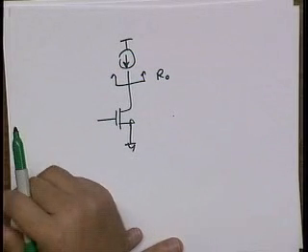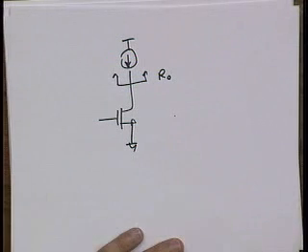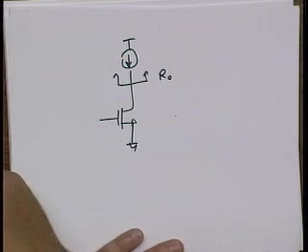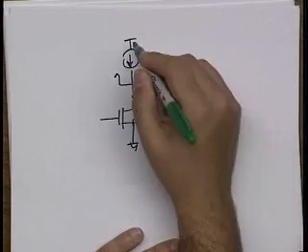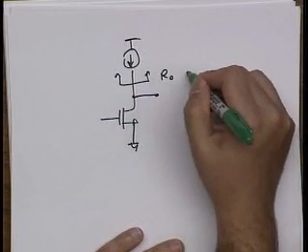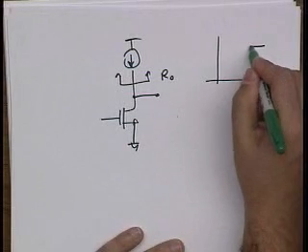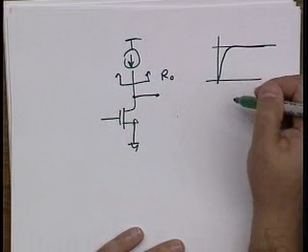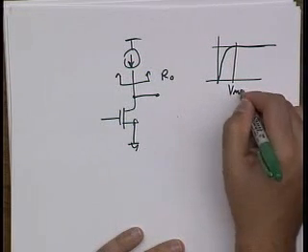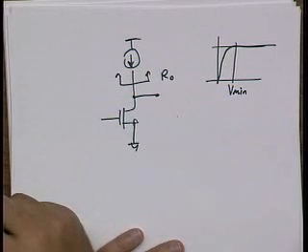What else do I care about? You could just say it. You don't have to use the mic. Swing, I heard. Very faintly, but I heard it. So swing. Basically, how far can I push this current source before it starts? If I look at the characteristics of this current source, it has very high impedance, and then it goes into a low impedance state. So this is Vmin, the minimum voltage I can apply across this current source and still keep it alive. Okay? What else?